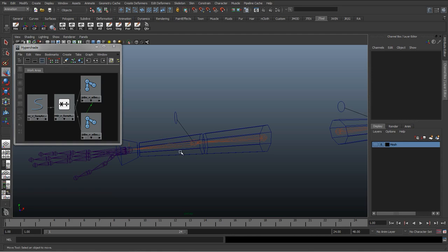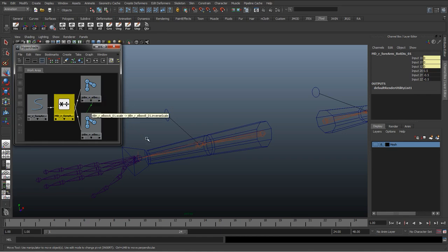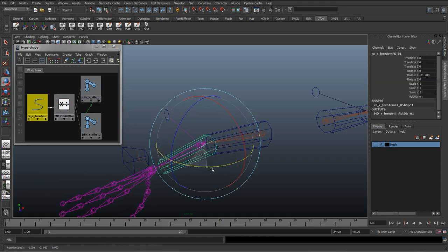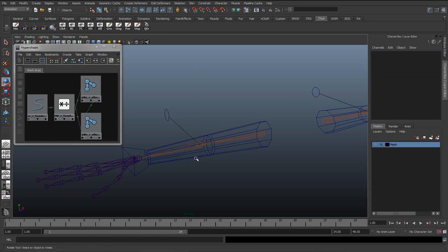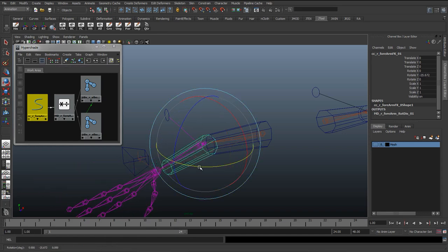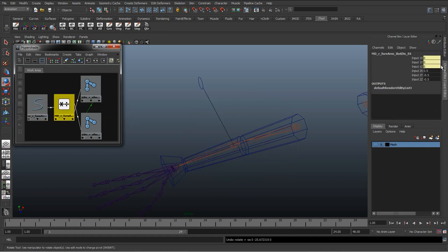Okay, first, for those of you that skipped the last tutorial and went ahead and did the right side yourself, one thing to mention from the tutorial is that when setting up this twist distribution, we set the values to negative 0.5 and negative 0.5 on Y and Z, just because the orientation of those joints is in the opposite direction. So if you had any trouble where rotating in Y was rotating the opposite direction, you just need to set up a negative value so it flips the values over.